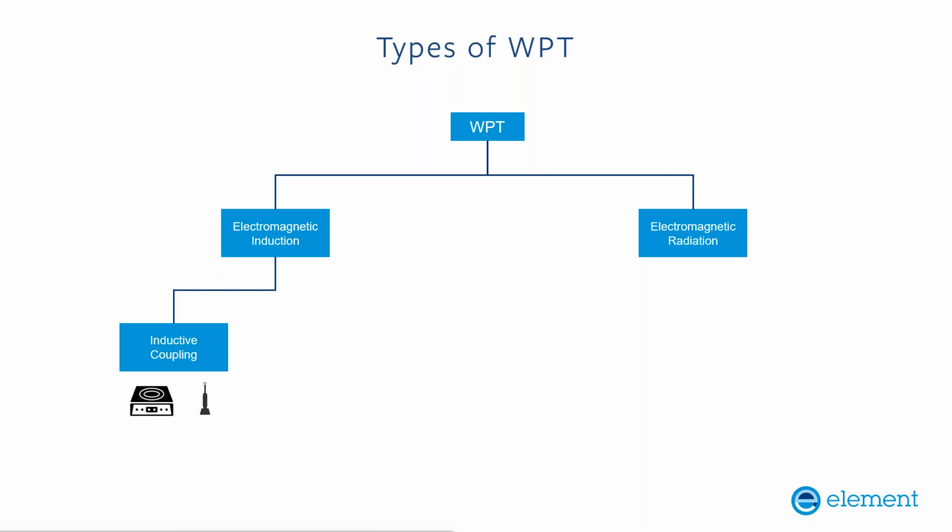And that coupling we typically see in perhaps legacy technologies such as induction cooking plates or inductively coupled and charged toothbrushes, those sorts of things, where the technology is really relatively simple, and effectively we're using it like a transformer, where the primary coil is embedded into one half and the load effectively is the secondary coil. So typically a ferrous metal providing the secondary of a transformer and providing coupling through that type of mechanism.